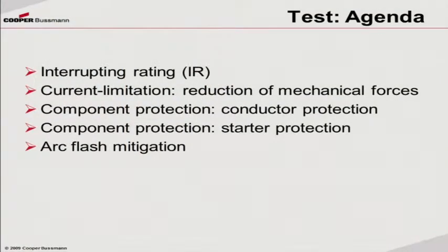switches, fuses, circuit breakers, contactors, everything that has to break current, turn it off, has a rating for what's the maximum short circuit current it can stop. And you can't exceed that rating or you will end up with catastrophic damage.